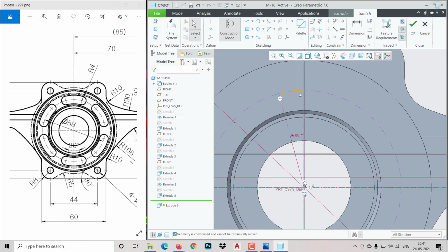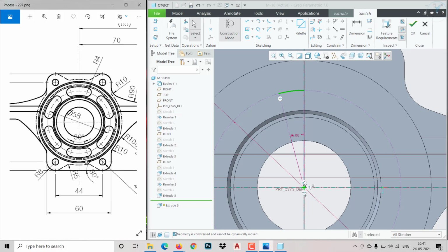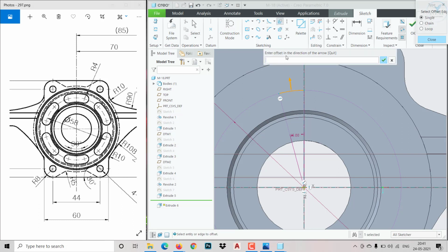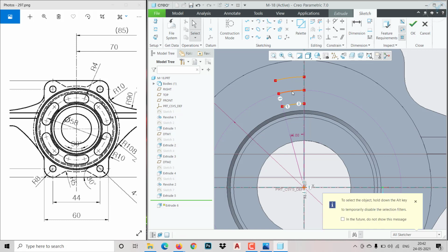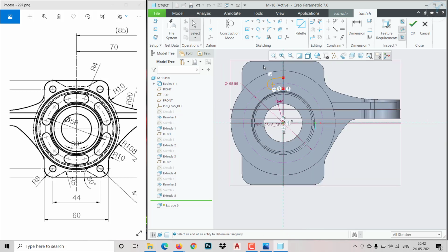Part will mirror it off. This portion, as you know, we need to make it a symmetrical one. So for that we need to know radius diameter 4. Radius is 4. So check this, use offset option, 4 mm outward and one more offset, -4. So now change this for construction. So then connect with this one and this one like this, then make this mirror.